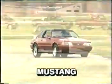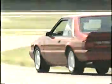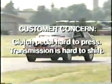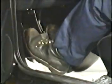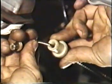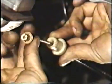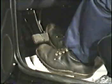With a cable clutch system, like the one on this Mustang, you may find problems with a sticking or non-releasing clutch. Typically, the customer concern will be that the clutch pedal is hard to press or the vehicle is hard to shift. In most cases, the feel of the pedal will tip you off that there is a clutch linkage problem. To be sure that it's not a cable problem, you should disconnect the clutch cable at the release arm. If the clutch control cable still sticks, the problem must be in the clutch controls.